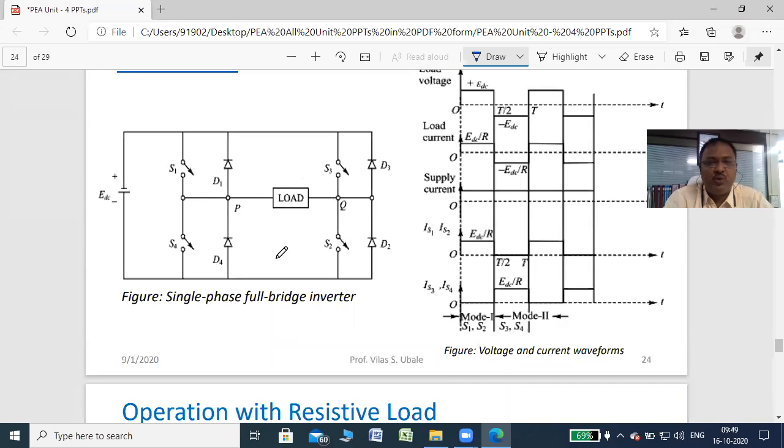All switches are off, no current. Then second case, when S1 is on and S2 is on, because the same trigger circuit is used. So when S1 is on, automatically S2 is also in the on state. Then current starts to flow. Again, the battery notation given in the circuit diagram is wrong. So upper terminal is positive, lower is negative, right?